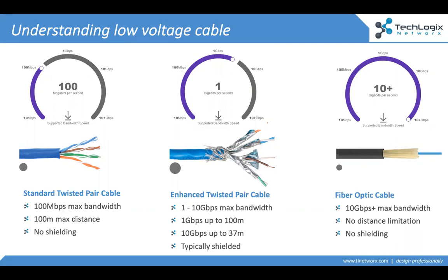Fiber historically was that telecom cable, that broadcast cable. Well, today we're putting it in the wall. And the nice thing about fiber is we don't have to worry about shielding. It's completely immune to interference. We don't have to worry about electrical issues. It's completely immune to static and surges and lightning, all kinds of issues that we traditionally see with a copper-based cable.